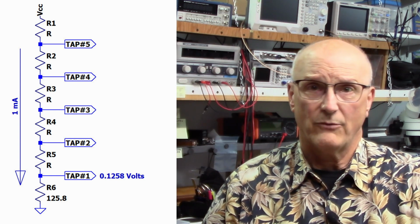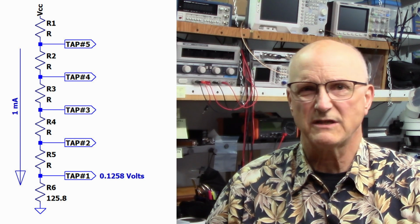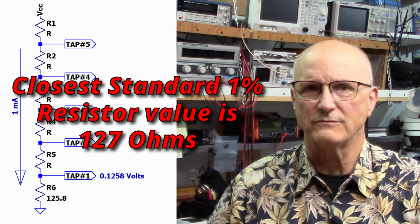Well, that's not exactly a standard resistor value. So we go out and we look for the standard 1% resistor value that might get close to this. The closest one is 127 ohms.